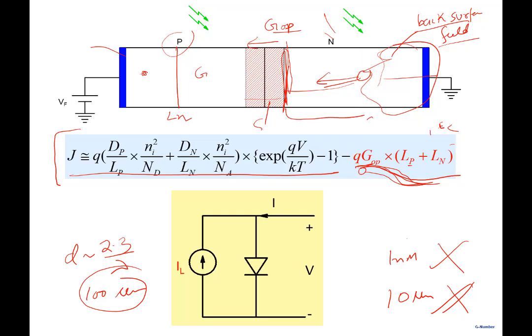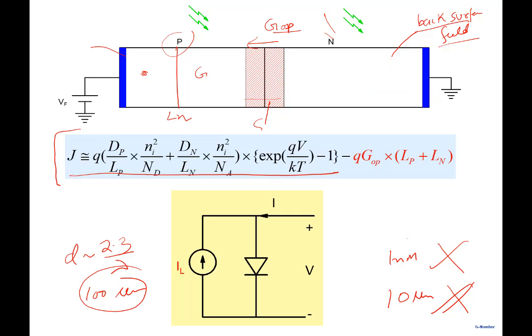So you have to note that if you are absorbing, we said the absorption length is of the order of 100 micron. So you need a diffusion length of the order of D also. The diffusion length has to be of that order to absorb everything. So you can do the calculation L equal to D, so L = square root of D tau, put in values here, how much lifetime do I need, okay? So that is what I have to do in order to collect. This is what this particular equation is telling you.